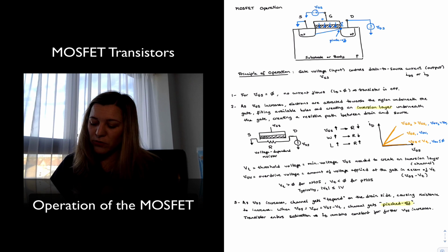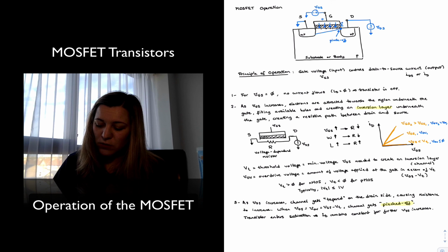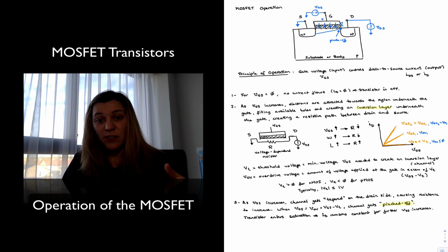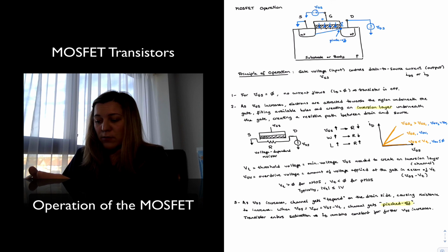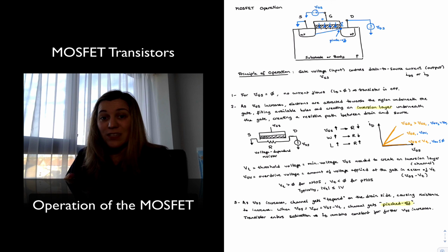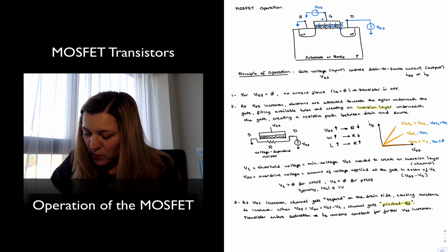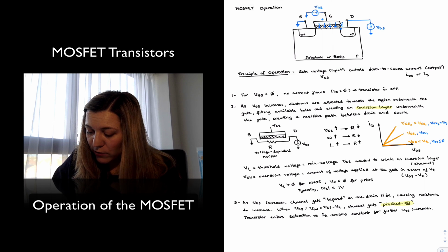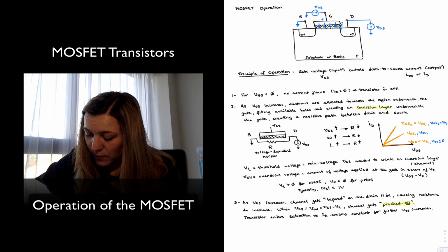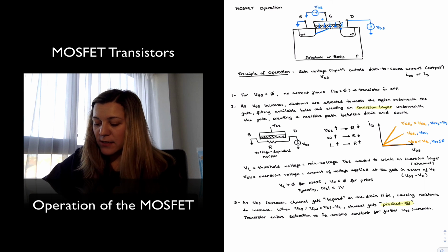And then if you approximate that the voltage at each point along the channel decreases progressively towards the voltage value of the source, then as you keep increasing VDS, more and more of the pathway from the drain to the source is going to be at a voltage greater than the overdrive voltage, and therefore the inversion layer is going to start receding. Okay, that's exactly what happens. If you keep increasing past the point where VDS is equal to the overdrive voltage, now your inversion layer, or your channel, starts receding back.